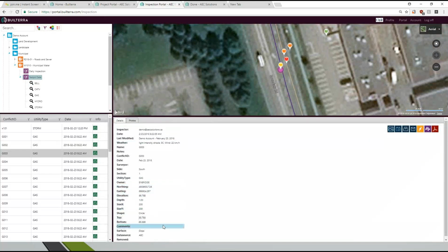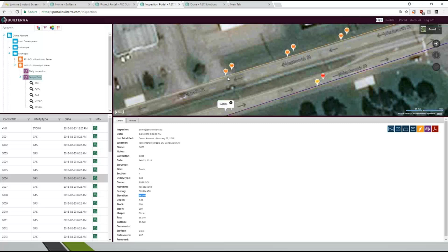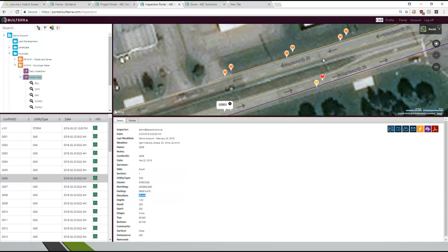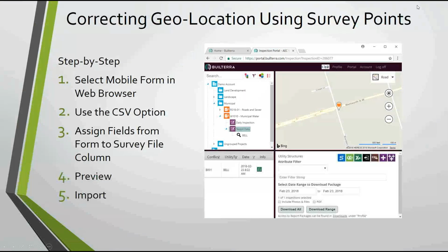So if you had a new surveyor go out and pick up this information, this is all happening in the merge. Okay. And of course, you'll notice that when you do merge the survey, if there's a UTM assigned, it will actually move to the as-built. So I did that for a reason in this sample: the markers will actually move from the cell phone location to the actual location. And once we have that, then we know we can safely import everything back into AutoCAD.